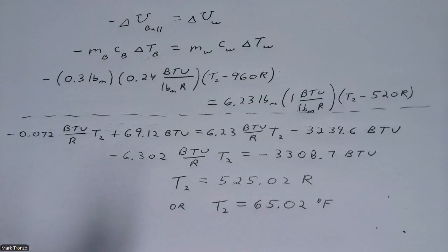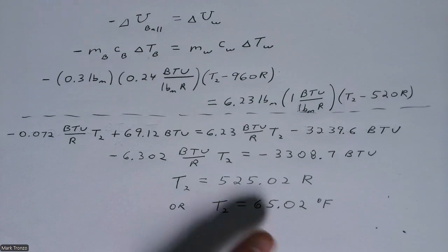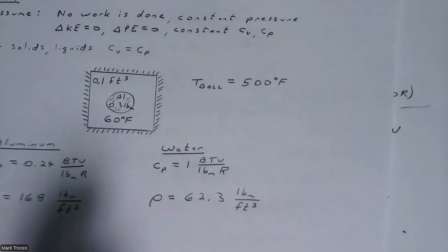And notice now the water temperature didn't change much. It started at 60 and it ended up at 65. So that CP value was probably correct to use.